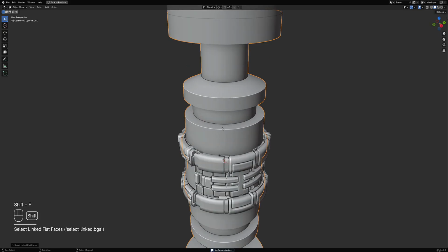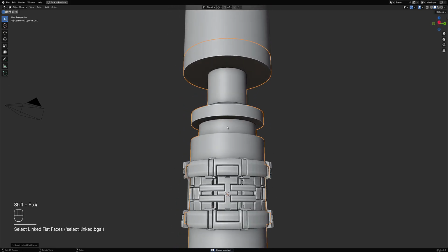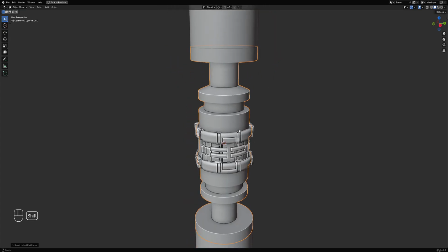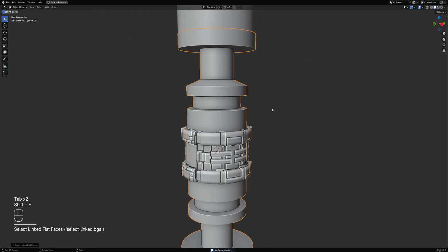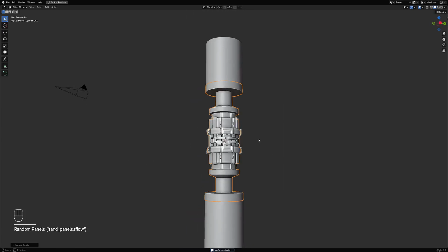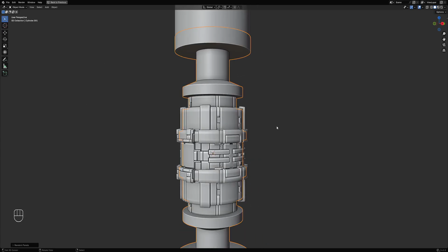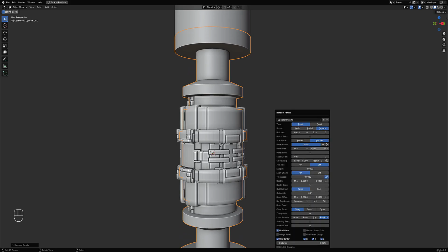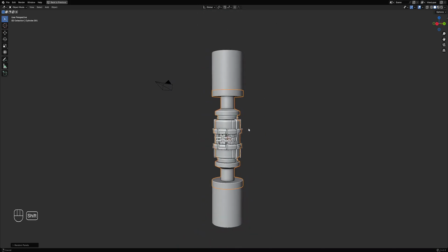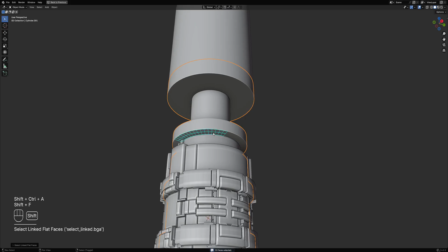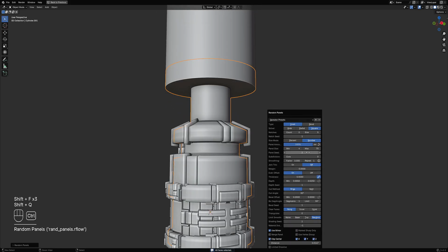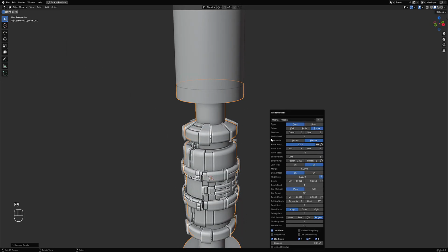And we need to select new faces. So you need to use the pre-select add-on on the real geometry side of the model, not the side which is mirrored. Okay, we need to create a balance between really detailed areas and also create areas which have the least detail and more relaxed areas like this one here. Let's hit A and let's continue on. So with the pre-select add-on, you can continue to just layer design in object mode without ever going to edit mode, and just use the add-on on the base mesh.